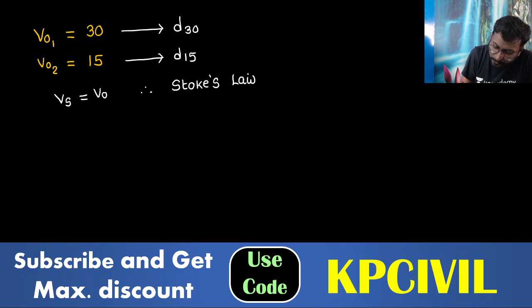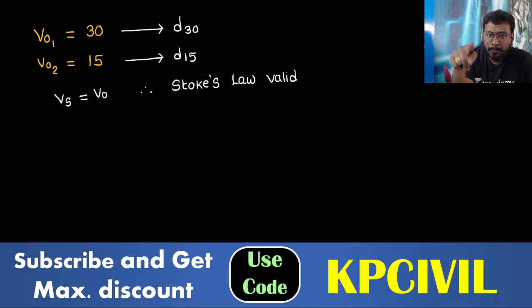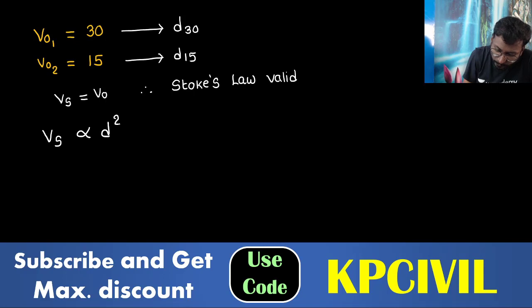Type 1 settling, Stokes law valid condition, and also they mentioned laminar flow. So we'll consider Vs is equal to V0 and Stokes law valid. In such a case, Vs directly proportional to D square.